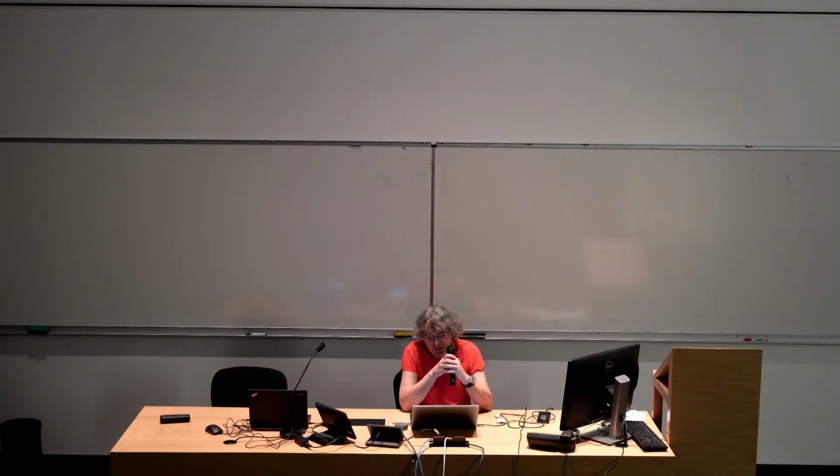Yeah. Since the complete emulation of that sort of effect was way too complicated, you can't do it here, but the effect would be that for each type of tape, you would need different bias levels. So when doing the recording alignment, the bias was the first thing you needed to adjust. There were different methods to do that.